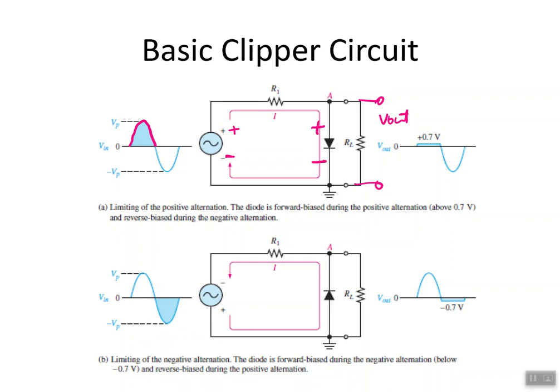Okay, so when it's forward biased, we know that the diode will be on if that supply voltage gets above the 0.7 volt voltage of the diode, right? The forward bias diode. So once it does, the output here is going to be limited to that 0.7 volts once this diode is on, right? And that's why for the positive cycle, you see that it gets limited. It rises up till it hits that 0.7 and then it gets limited there, okay?